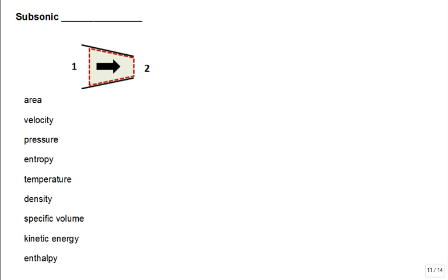Now, this is one thing I would encourage you to do, is go slow. You say, I noticed this device, its flow is going from 1 to 2 in it. What's the area doing? The area 2 compared to the area 1. Area 1 is the inlet, area 2 is the outlet. Is the area 2 less than the area 1? Yeah, that's what's happened. What device would we call this? A nozzle, a diffuser, a turbine, a compressor? What device? It's a nozzle. It's a nozzle, right?